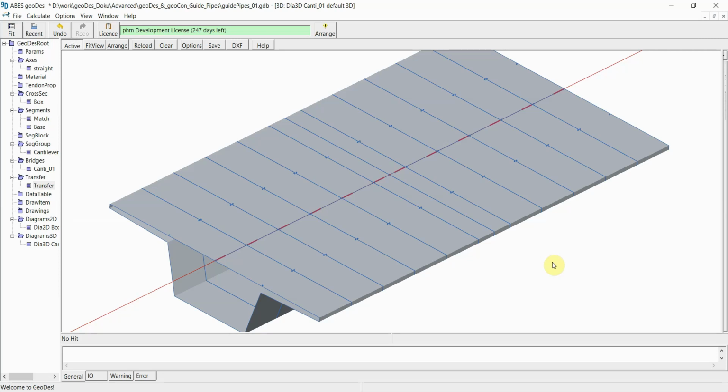The underlying technical challenge here is such that these guide pipes need to be placed in very precise spots, in order to fit with the pre-lengthened cables. Therefore the global coordinates and the exact specification for these anchors and guide pipes for these cables need to be kept, even when the segment itself deviates a little bit from the intended position.